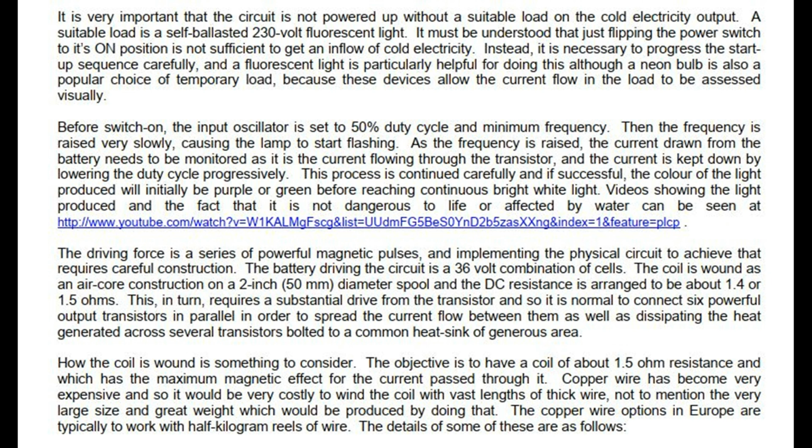The driving force is a series of powerful magnetic pulses, and implementing the physical circuit to achieve that requires careful construction. The battery driving the circuit is a 36-volt combination of cells. The coil is wound as an air core construction on a 2-inch, 50 mm, diameter spool, and the DC resistance is arranged to be about 1.4 or 1.5 ohms. This, in turn, requires a substantial drive from the transistor, and so it is normal to connect 6 powerful output transistors in parallel in order to spread the current flow between them, as well as dissipating the heat generated across several transistors bolted to a common heatsink of generous area.